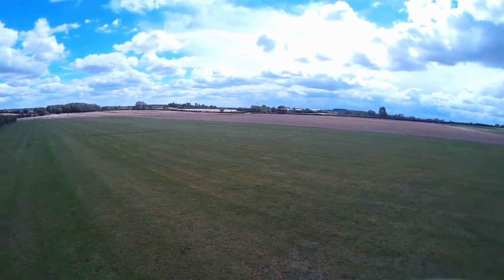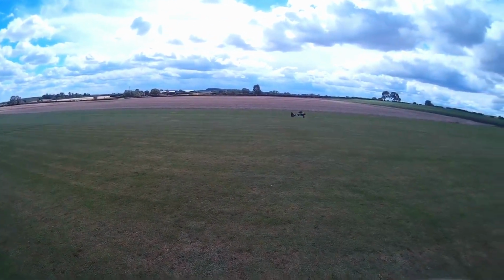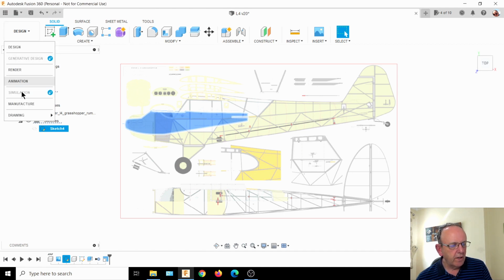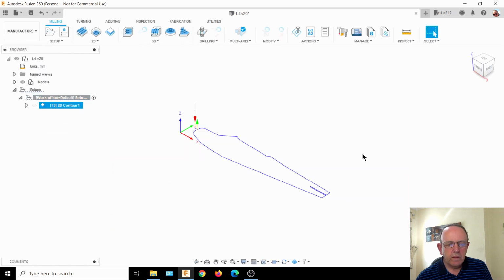Basically, what I've done is create a sketch. The sketch looks a bit small at the moment because I've since scaled it for some testing. If you know anything about Fusion 360, you do design and then you go into manufacture. Normally Fusion 360 will only, as you can see here, have X, Y and Z, or Z if you're in the States. And all I want is the X and Y just copied over to the U and Z.